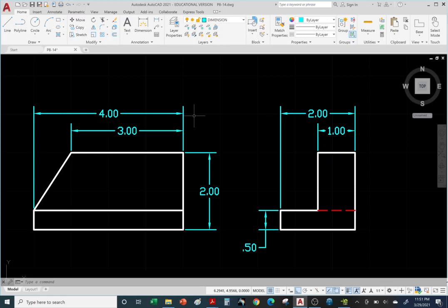So when dealing with holes where you want a tight fit diameter and control it, you will go to 3 decimal places on the diameter of a hole, and maybe even up to 4 decimal places. But typically 2 decimal places is the way to start. Then you can work your way to 3, maybe 4 decimal places, depending on the function of the circular hole, depending on what type of fastener you're going to put, whether it's a bolt, a dowel pin, etc.